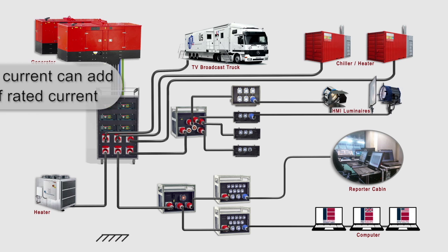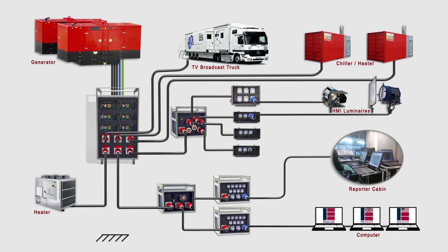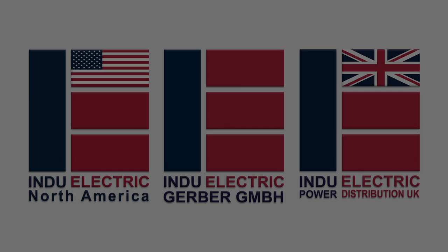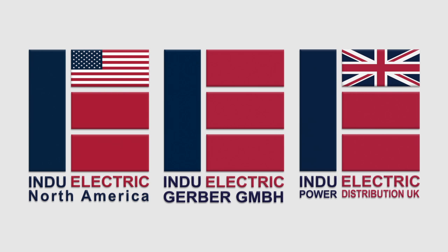We are now at the end of our session and hope that we were able to give you a better understanding of earth leakage protection and how to adjust the RCD monitors accordingly to each individual field setup. Please remember that each field application is unique and will require individual settings that need to be determined.